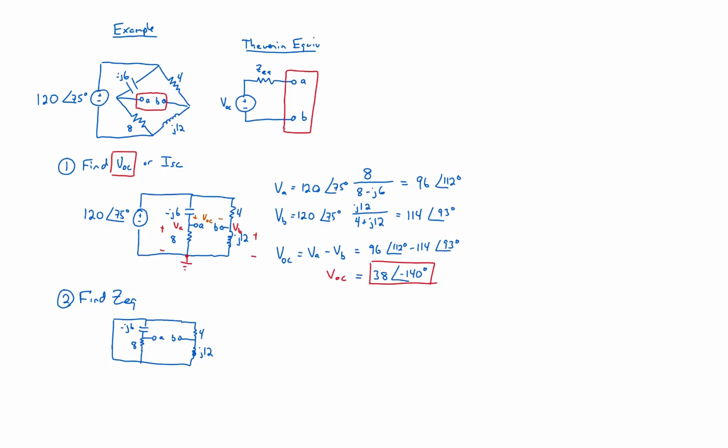If you look at this long enough, though, you can see something interesting, that this capacitor and this resistor actually are in parallel because they are connected at both ends. They're connected on this end, but they're also connected at that end. And we can make the same argument about the two components on the right. They're connected here, but they're also connected at the other lavender end. So all we need to do is somehow redraw this to make it clearer. And let me try my hand at redrawing it.